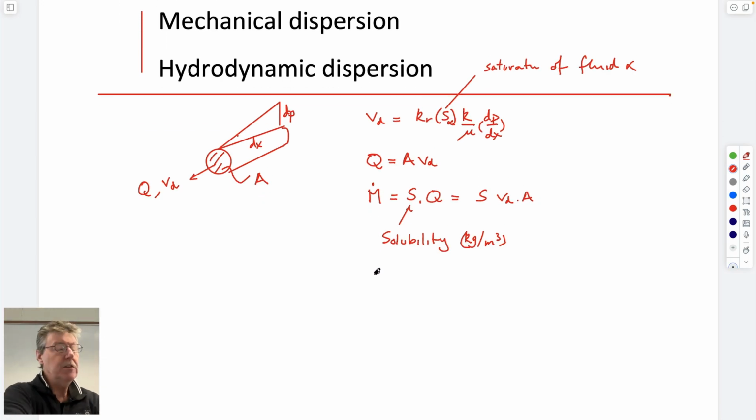Certainly you've looked at velocities, and so you've also looked at advective velocities. And you've looked at the advective velocity is equal to the Darcy velocity. I know it's an alphabet soup. Darcy velocity is what comes from Darcy's law. Advective velocity is the velocity it actually travels with if you were to calculate how far it would go.